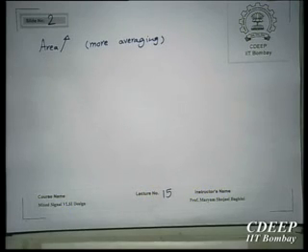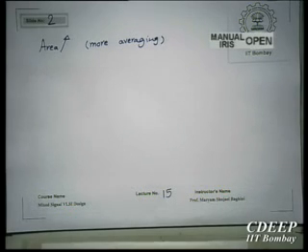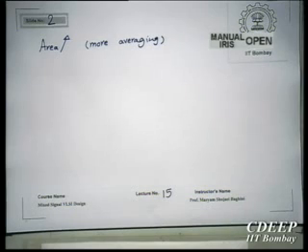Consider you have a transistor and its area is W into L. You divide this transistor into an array of, or parallel combination of, or series combination of smaller transistors. Each one of them is like a sample in this statistical domain. Now you are increasing the number of samples. Therefore, you are doing averaging over more number of samples, so it is likely to have a better value of matching.